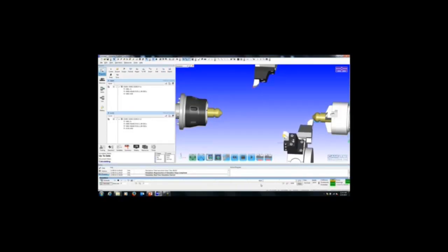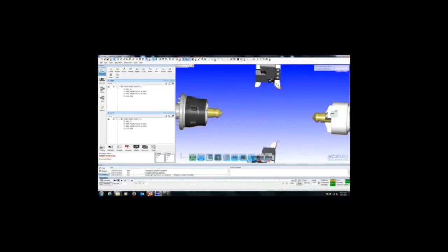Works so well, I think I'll go ahead and do it for the right side spindle, sub-spindle as well. Take that tool path, drag it up to the top, copy it. I don't need to reverse these in arcs. Pick another tool position for number 2. Generate it.